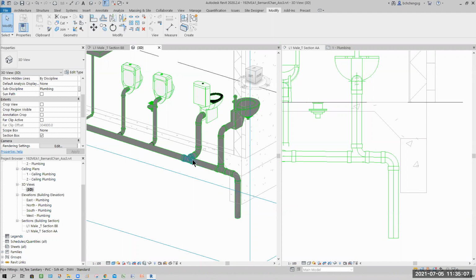Because if this is too long, things get stuck or stained there, and in future the water flow will also not be smooth. Although by default the pipe has a coating inside which is very smooth, after a while of usage it wears, and the pipe will start to stain there. So next time when you flush, you might not fully clear it and it starts to accumulate.